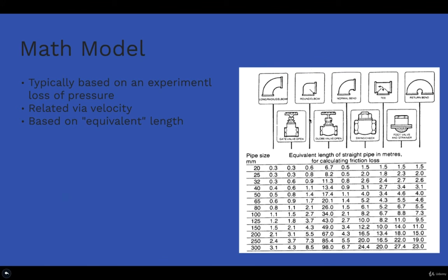And well, we're not going to do any exercise, but what I want you to imagine is how these and these right here relate to each other. Both do the same work, which is bending or moving the fluid flow to the right, but this one is very smooth. Actually, it's called a long radius because it will have less friction loss than this one right here, which crashes directly into this wall and then moves to the right.